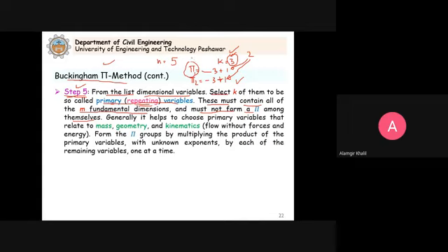It will not be possible. These 3 plus 1, these 4 together should make a dimensionless group. This is what pi means, that it is a dimensionless product group. So when you select the 3, among themselves they should not make a dimensionless group. But when combined with the other remaining 1, it should make a dimensionless group. So we have to select in this fashion.